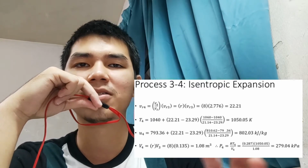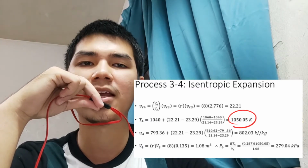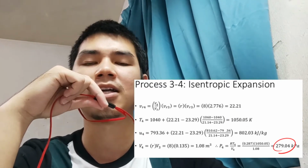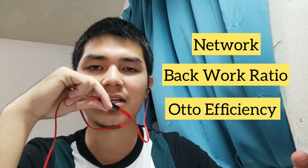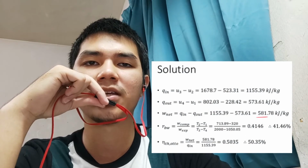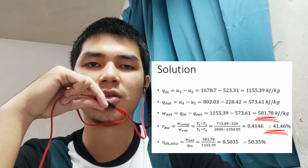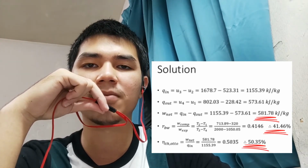So we got the temperature 4 is 1050.05 Kelvin and the pressure 4 is 279.04 kilopascal. And going back to our main question, which is to calculate the net work, back work ratio and the Otto cycle efficiency: the net work we got is 581.78 kilojoule per kilogram, the back work ratio is 41.40% and the Otto cycle efficiency we got is 50.35%.